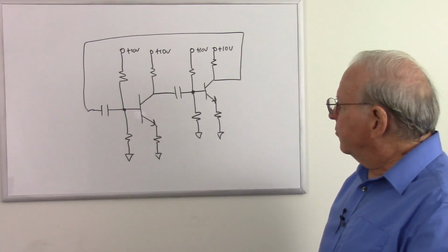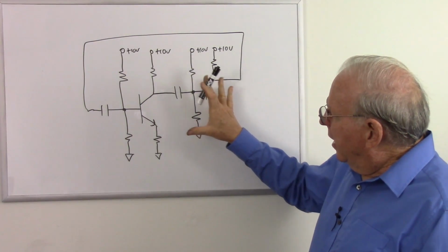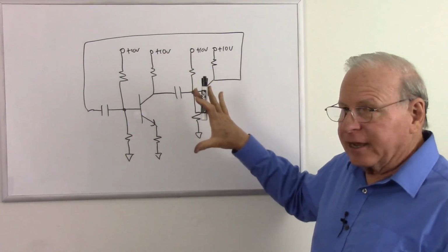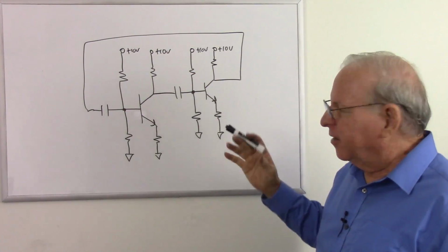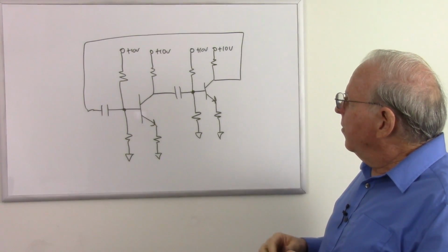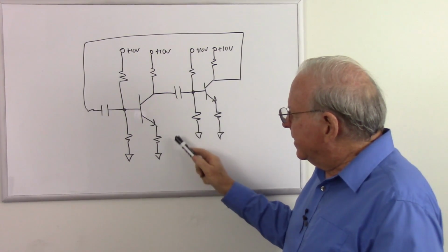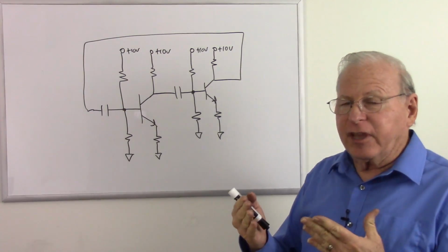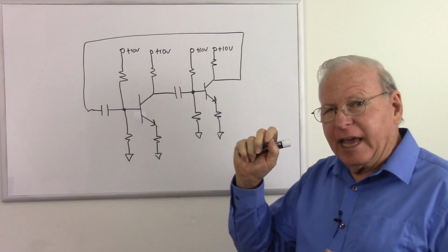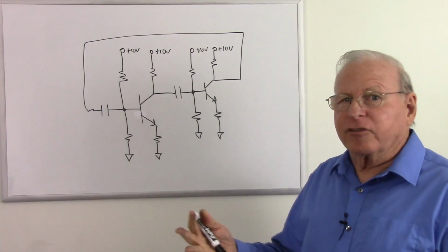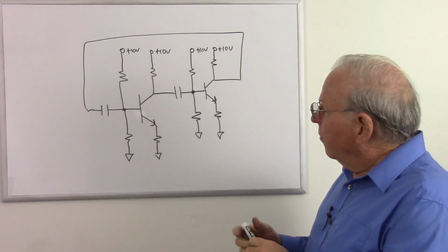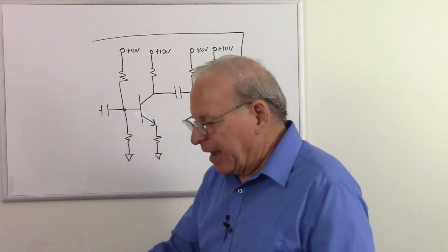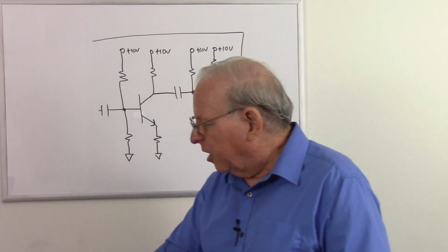So we're starting out with this circuit, and this will work as it is, although the working circuit I'll show a schematic of has some of the components missing, but that doesn't really matter. So what are we going to do? We want to control the gain of this, but controlling the gain alone is really not a good way to get sine waves, because as I said, if you reduce the gain the tiniest bit too far, it'll just simply stop oscillating. So what we're going to do is add some circuitry to the feedback, and this is just a different way of drawing the Wien-bridge oscillator.